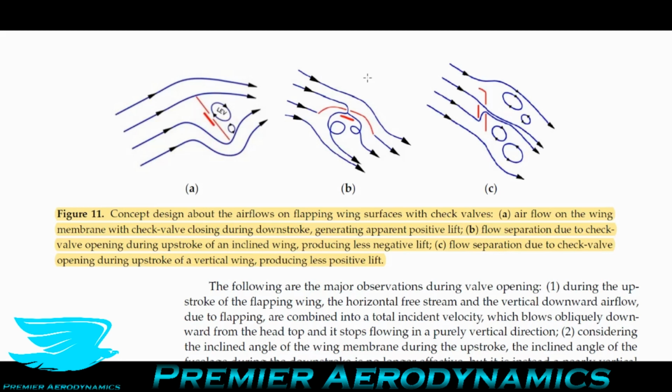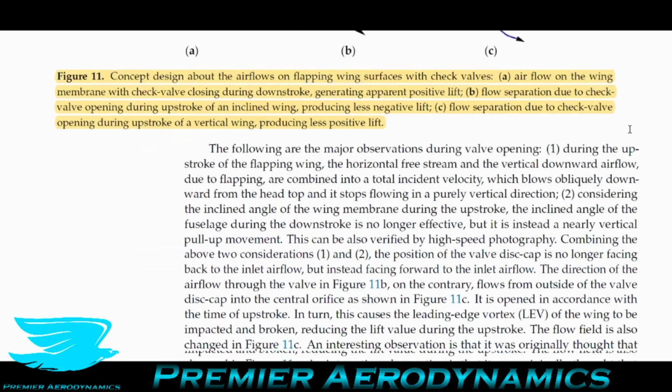And now the lift being produced from that leading edge vortex is no longer there, which is one of the major reasons why probably on the upstroke, the lift isn't being produced as much anymore. The leading edge vortex has changed. It's no longer there. The flow physics has changed, so the lift production has dramatically dropped. So not only has effectively the area that this wing sweeps over become a little bit smaller, the flow physics is completely different, for multiple reasons.